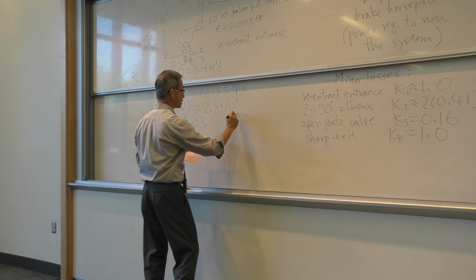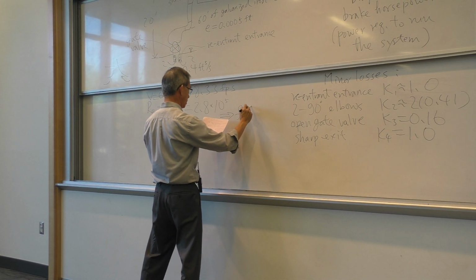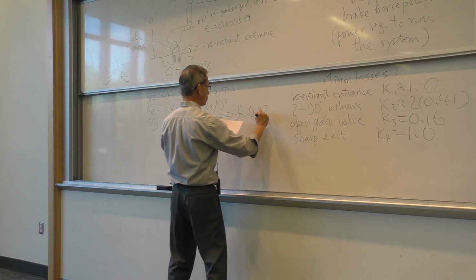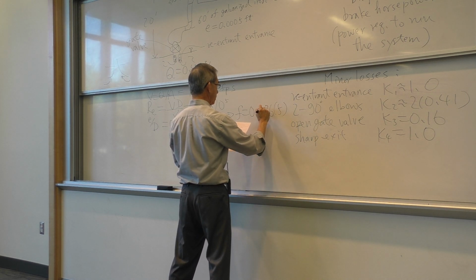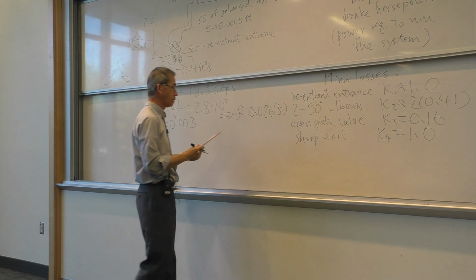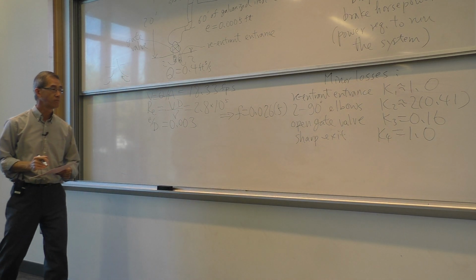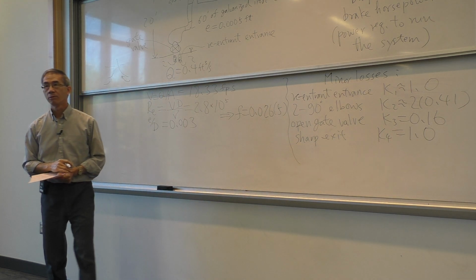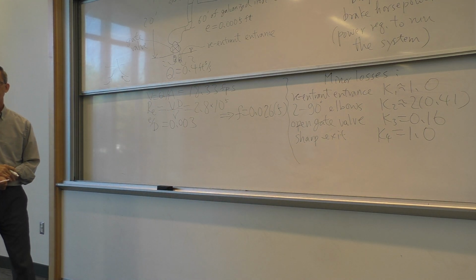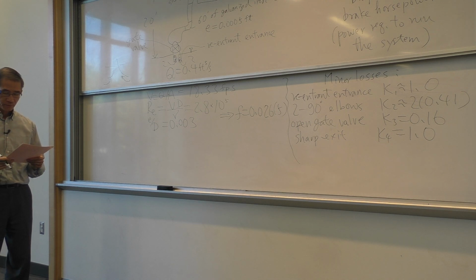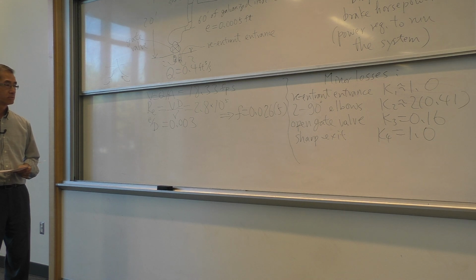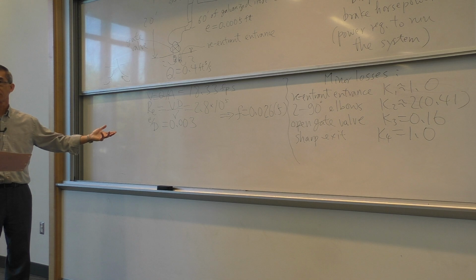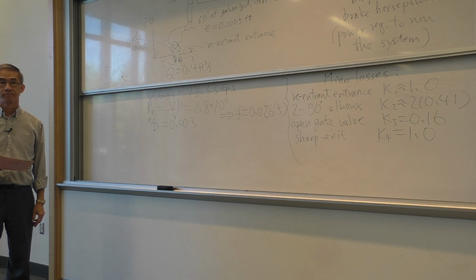So that is sufficient to put me on the Moody diagram, of which I will read and look up. And I want you to verify this at home. The friction factor approximately is about 0.026. That's close enough. The 5 at the last digit is not critical. So up to this point, nothing new. Let me stop and make sure you understand this. Can you do this? Yes?